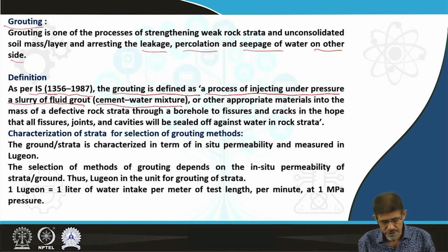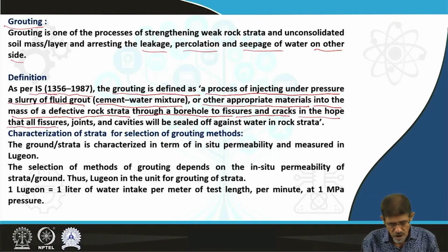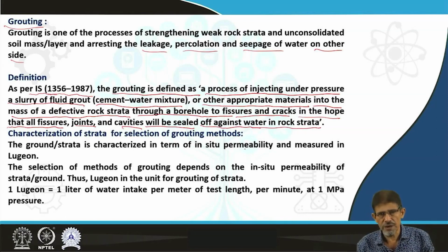A cement water mixture is recognized as fluid grout, or other appropriate material used for the same purpose, into the mass of defective rock strata through a borehole to fissures and cracks, in the hope that all fissures, joints, cavities and all kinds of discontinuities will be sealed off against water in rock strata.